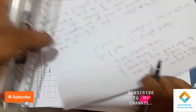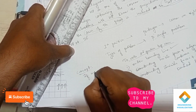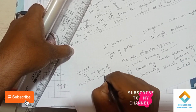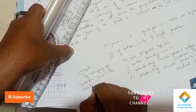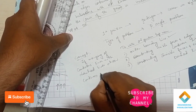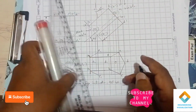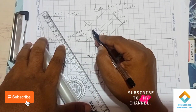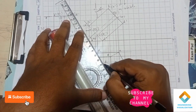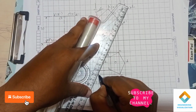So here there is a concept: if there is a merging of continuous line with the dashed line, we need to show only the continuous line. That means we will be showing only a part of the pentagon with the dashed line here, because already we have constructed a part of the pentagon with the continuous line. The remaining part we will be constructing using the dashed line here. So try to join with the dashed line here.